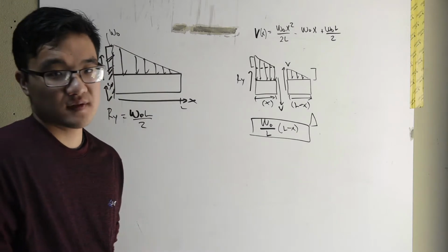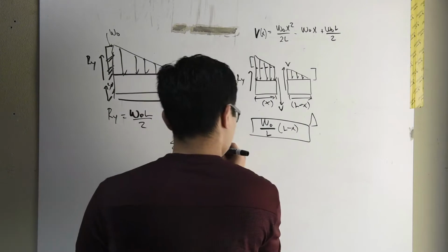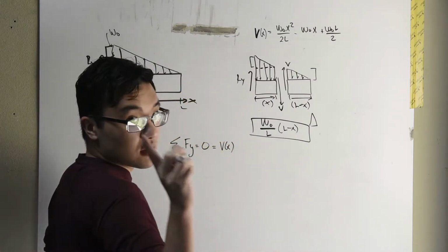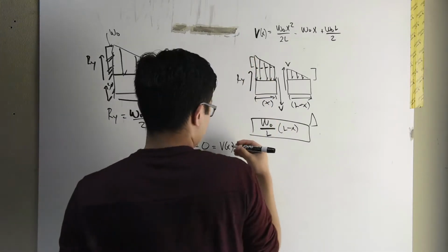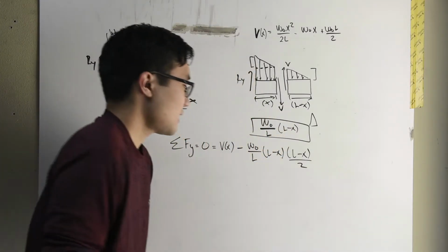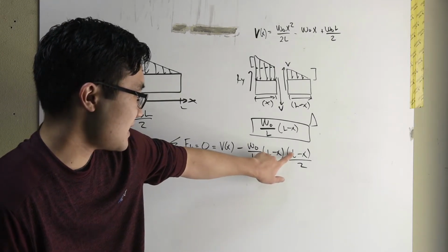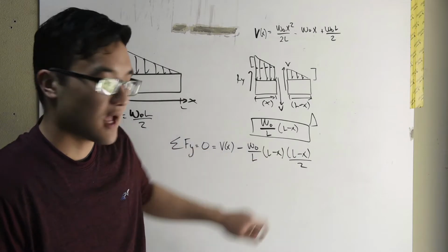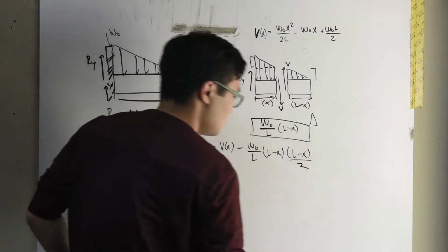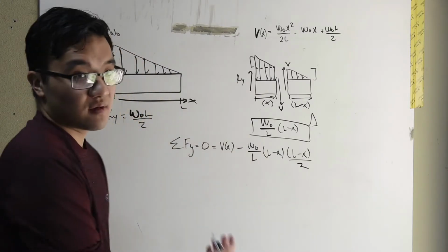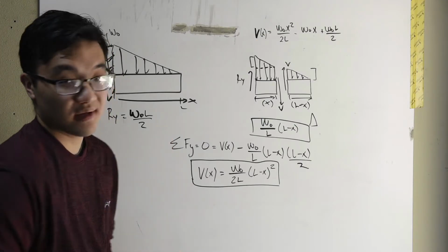Now all we do is our force balance, same as before. Remember, shear is positive here. Shear is in the positive y direction, that is. Okay, and remember, this is the height, this is the base, that is the 1/2. That's the equation for a triangle. So now all we have to do is solve this equation. Now that's a lot easier than solving it there.